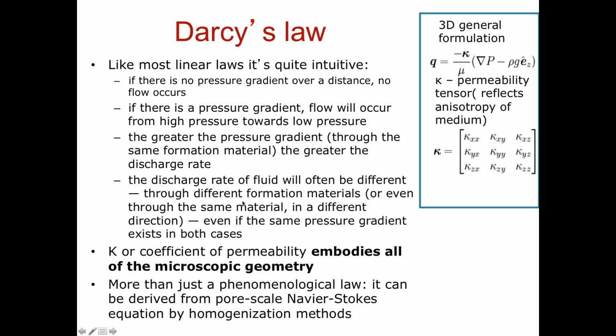This is work separate from Darcy, but basically you can find online Whittaker's 1984 or so proof that you can actually derive Darcy's law from pore scale Navier-Stokes equation applied to a periodic sphere packing of equal spheres. Okay. So basically, it's more than just phenomenological. Again, I mentioned that at the very beginning of the class. When you actually have something that was experimentally measured that's just postulated as a law, and then you also have a separate theoretical proof, which if you separately derive it from Navier-Stokes equation from the pore scale considerations, then it's really that much stronger result, and basically what you observed experimentally really captured something essential.